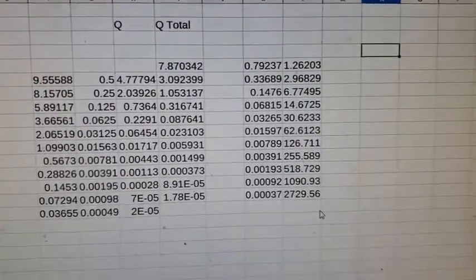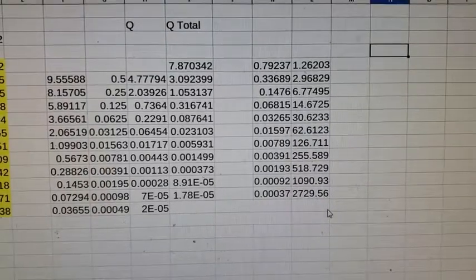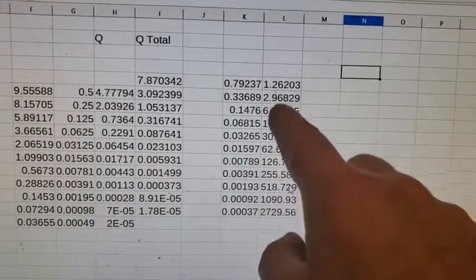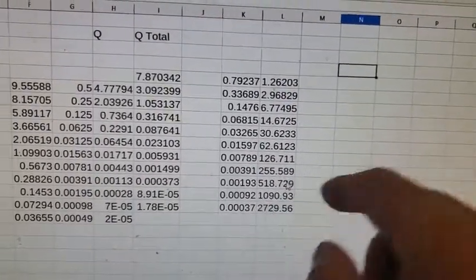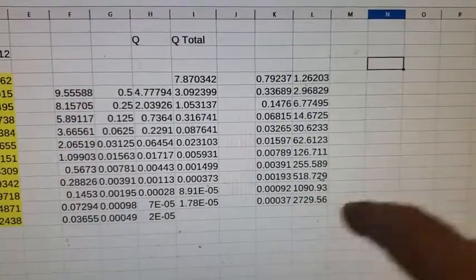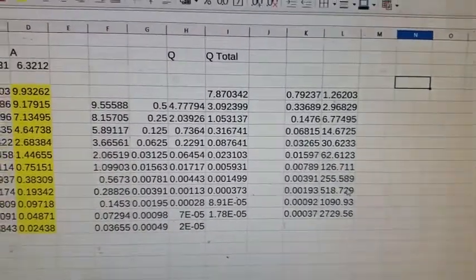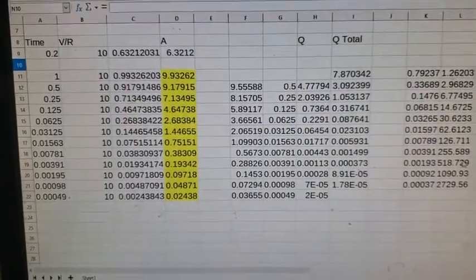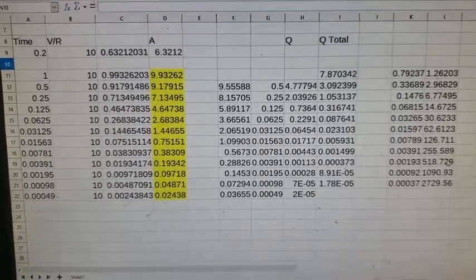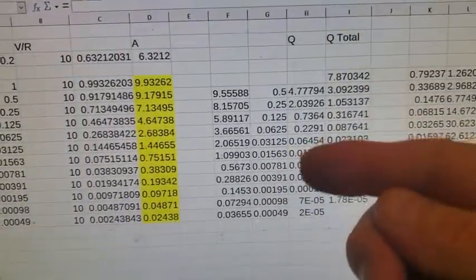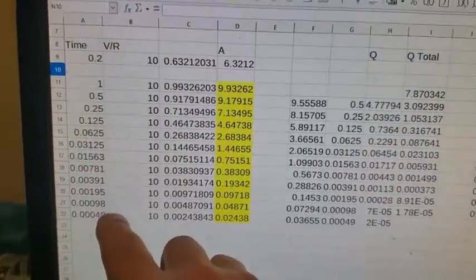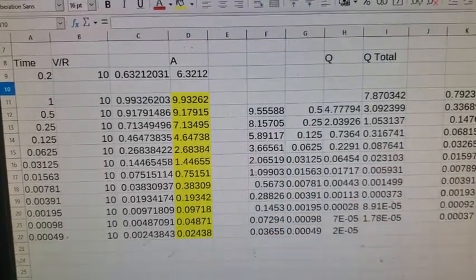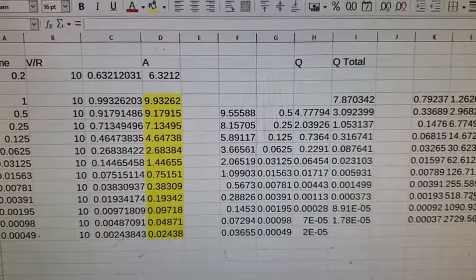But to make that work with a DC-DC converter, where you start to get out to here, you run into other issues. You run into the resonance, you run into skin effect, you run into what can your components do when they're going fast. So again, the bottleneck very often might not be the coil when you're going this fast. The bottleneck might be your transistor, whatever your switch is. So that's something to keep in mind.